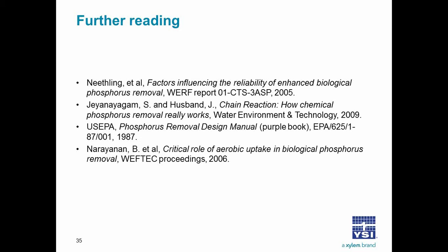Good question. So the benefit of feed-forward control is the lowest possible chemical consumption by perfectly matching the chemical dosage to the chemical requirement. It differs from feedback control in that you're monitoring upstream from the dosage point, and you also require a model to predict what that dosage should be. Whereas with feedback, you're merely increasing or decreasing the dosing rate with the feedback from the analyzer.